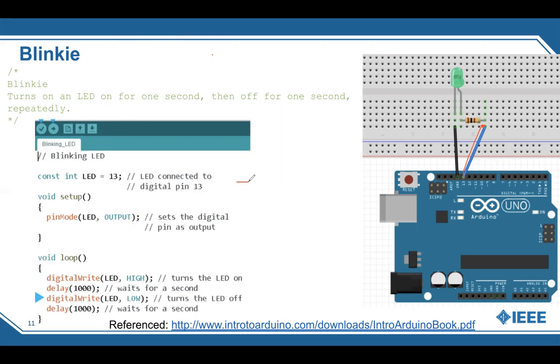Okay, so sorry, guys. I have this plus 5 volt source, which is giving 40 milliamps coming from this Arduino. And then I connect that in the breadboard to the resistor, and then I connect it to the LED. And so then we have our LED here, and then we have it connected to a ground pin.